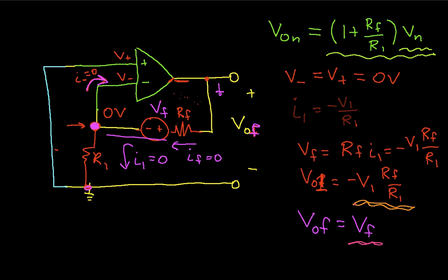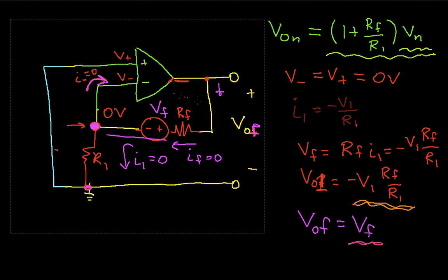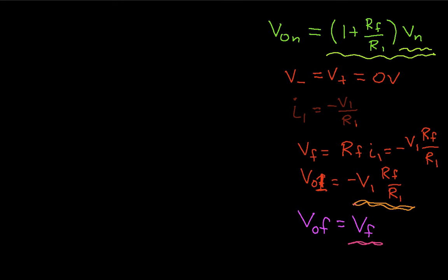So we'll actually get rid of the messy circuit diagram here and use the extra space to compute the output RMS noise value. The output RMS noise value will be the square root of the 3 different noises that I've computed, each of those squared.